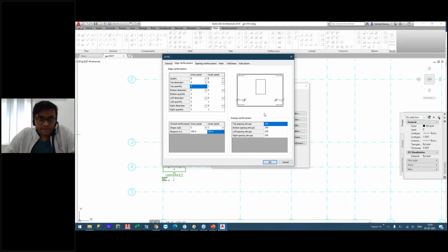And this end cap reinforcement, so whenever we add the end cap to our walls, if we do have the reinforcement in that particular end cap, it will be placed according to these distances that are presented: 30, 50, 70 and 70 for the different edges of the wall.